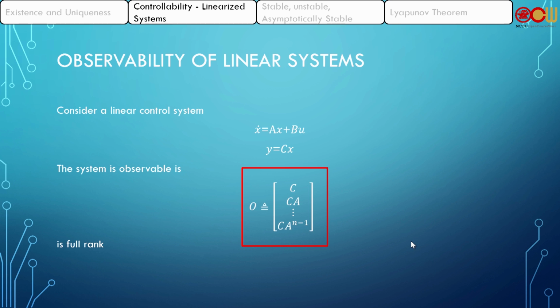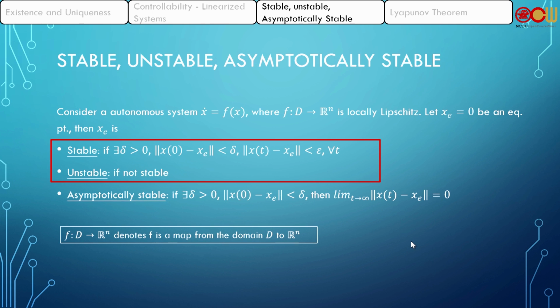So in the matrix, you replace B by C. In controllability, we evaluate B, AB, right? Here it is C, CA. You just replace B by C. Because A remains the same, right? A is here and here, because A is the propagation of states between different times. Okay, A is the natural dynamics. But C depends on which element the input is from, same as B here. Okay. So here's controllability, and we have mentioned this before.